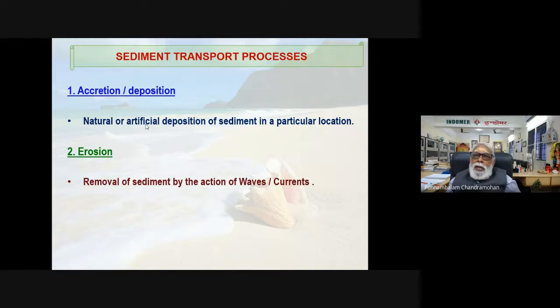Any coastal form, if you see, is not a stable form. They are all in a semi-equilibrium condition. Tide to tide, they will change the coastal formation, not to a very great extent, but to some extent. During high tide, you will have some accumulation. During low tide, you will have some erosion. If you have a beach profile, you can see that. Also month to month, you will have a change in the wave climate, and accordingly different geometrical features of the coastline.